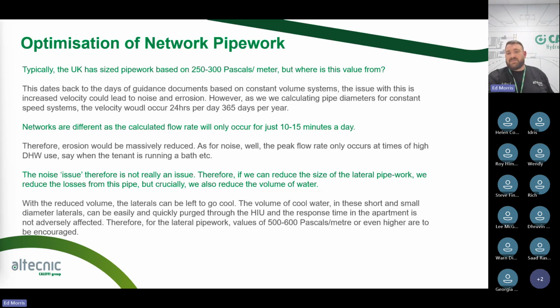So your diversity factor has to be applied across the whole network. Because if you've got one central plant feeding 4 blocks, you're still essentially feeding one system, although they can be fed from separate blocks. So your diversity factor will be applied across the whole development because we're looking at the energy efficiency across the whole network per se. So we'd have to take it from all 4 blocks as being one identical system, not each block or each riser itself.